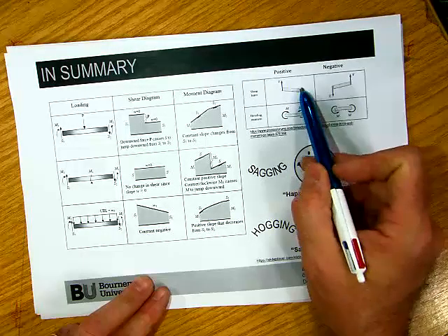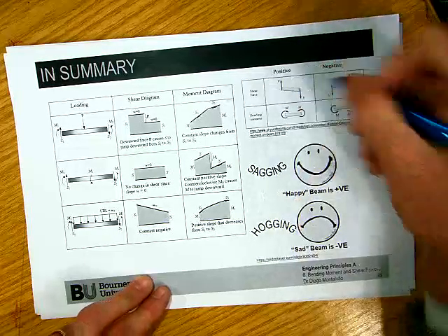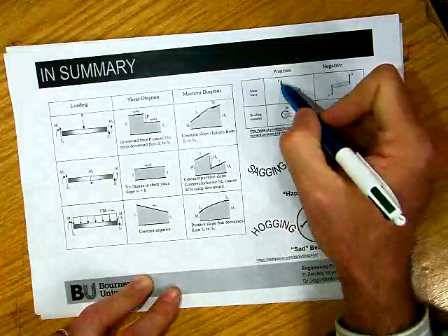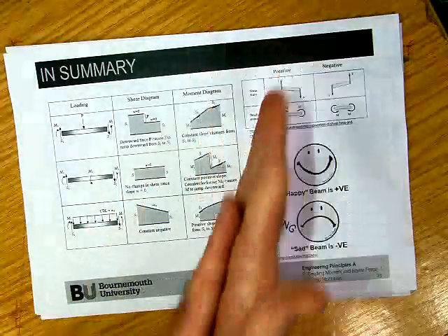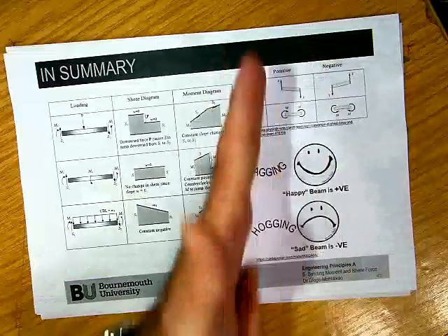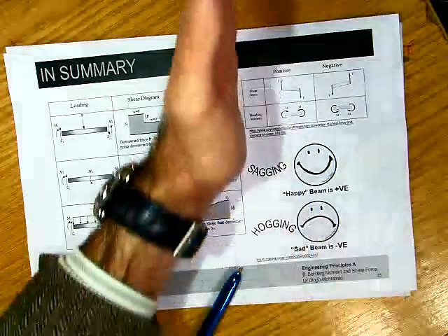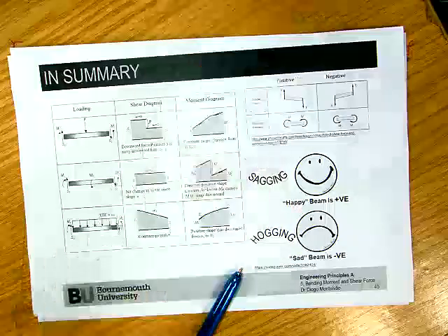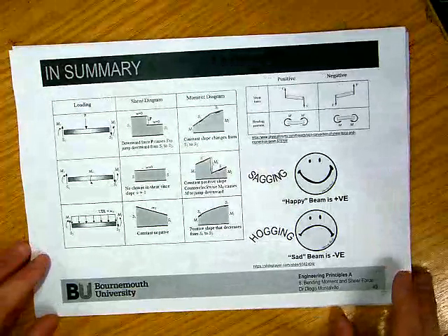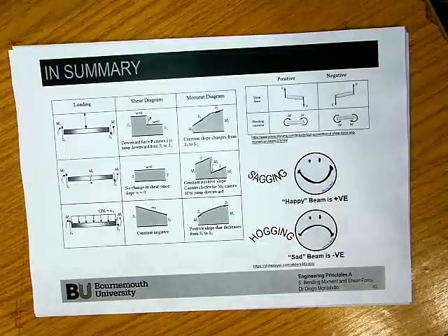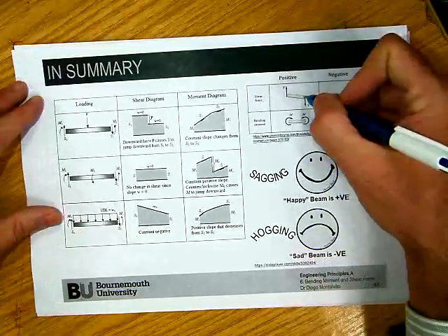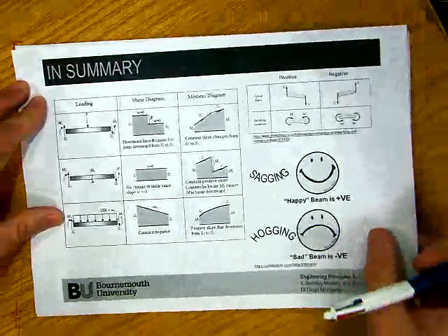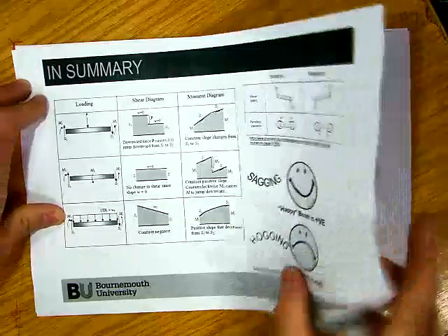For the shear, the positive one points down when it is represented on the right, and points up when it is represented on the left. If you think about hands doing this motion, one hand goes in one direction, the other in the other direction. That's the positive shear. To have shear, you have to have two surfaces moving in relation to one another. So I need to keep this in mind.